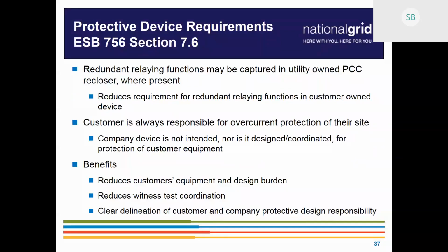On your site, you're still going to need protection. So if you feel you need any of those elements that we've moved, which would be the over and under voltage and the over and under frequency, by all means, you're able to put those in there, and we'll do the best we can to coordinate with those, or even your overcurrent elements. But just be aware that we do still have the ability to change our settings whenever we need to, based on system conditions. So we'll do the best we can to coordinate, but it's not always going to be the case. But you definitely need the overcurrent protection.